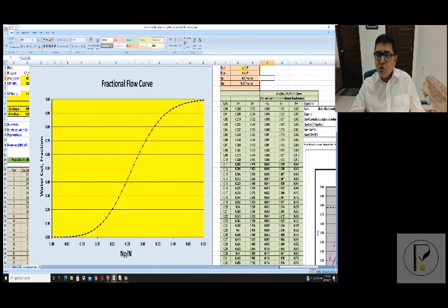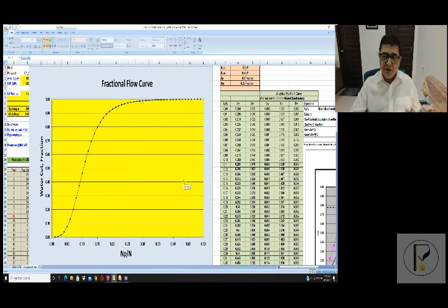So let's go back now to the original condition of 0.3, and water viscosity I'm not changing, let's keep it almost constant. Now we can increase the oil to around 50 centipoise. Now we are entering from light to medium gravity oil. Now you can see the fractional flow curve shifting to the left. That means early water breakthrough. Now the displacement is getting unstable. The mobility contrast is more than 100. So water is tending to move 100 times faster than the oil for the same drawdown.